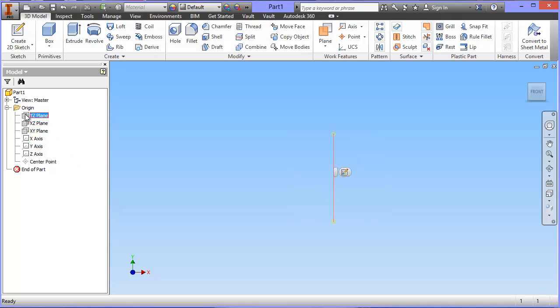And if you hover over any of these things, let's put this into the isometric mode so you can see them. They show you what those planes are. And basically what it means is that we can work on any of these. We have an X, Y and a Z, and one will represent the front, one will represent the side, and one represents the kind of the bottom or the top. We have to decide which one we're going to work on when we want to design something.